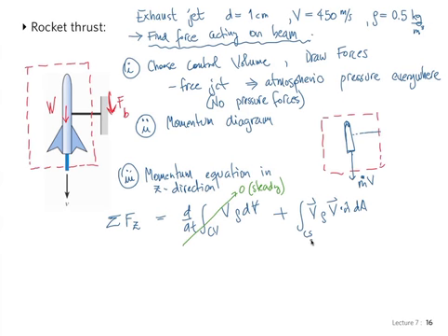This is in the control surface. So this is just, in this case, the flow of momentum. And there's only one flow of momentum, minus rho a v squared, the velocity squared of that jet, which is a momentum outflow. The minus sign is because the velocity points outward, negative in the z direction, basically.